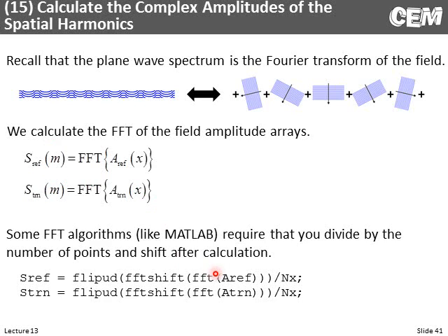Now, here's the trick in doing that. We calculate the FFT, that's pretty straightforward. Because of the way MATLAB calculates the FFT, it's scaled by the number of points. So we need to divide by the number of points to scale it correctly.